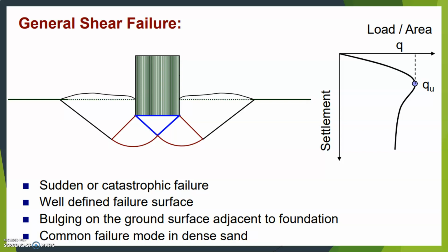Ultimately, the state of plastic equilibrium is fully developed throughout the soil above the failure surfaces. The failure is accompanied by the appearance of failure surfaces and by considerable bulging of the sheared mass of soil. However, in this case, the final slip movement would occur only on one side,